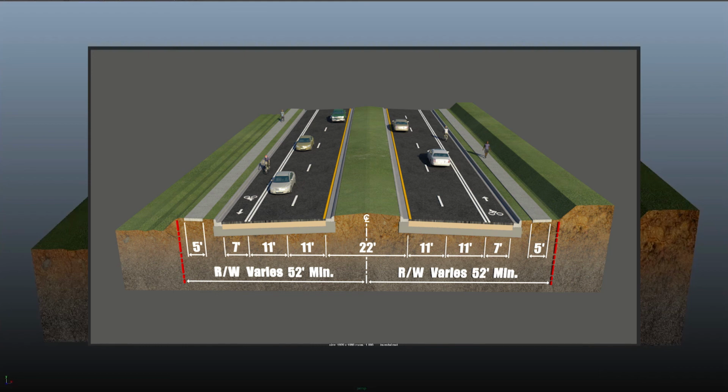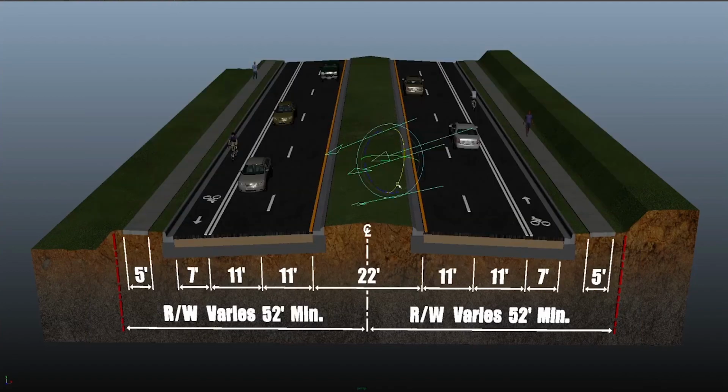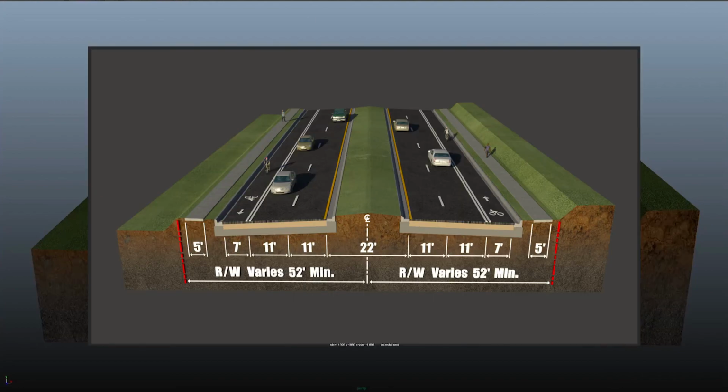So what I'll probably do, instead of really tweaking the lighting and messing with it much, just rotate the direction of the sunlight so it's going on top of that shape there and not casting a shadow on it. Let's change the sunlight. Let's go the other direction so it's actually shining on that bank. And then render. There we go. Now we have our 3D typical.